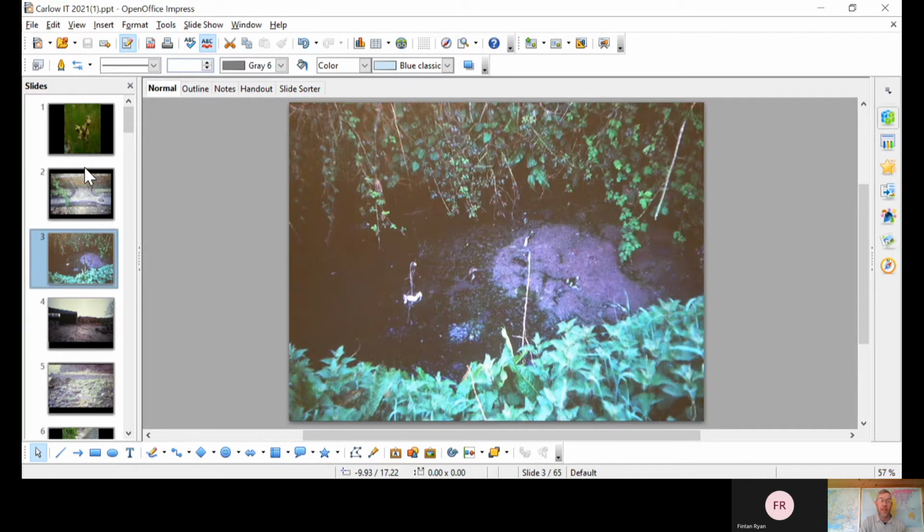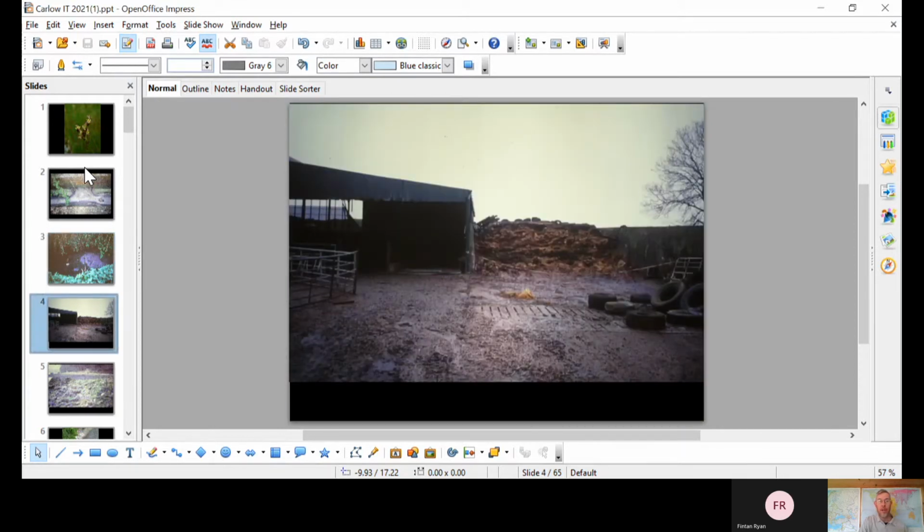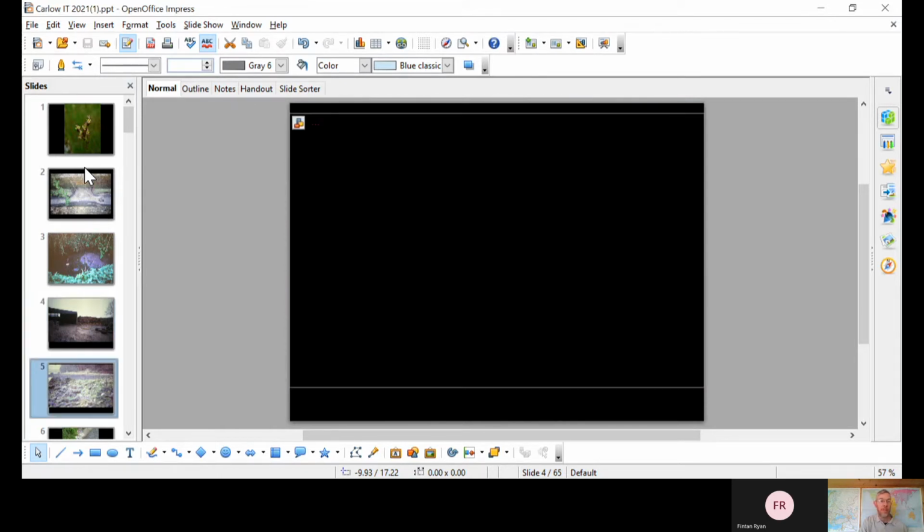That literally, it was just stripping the oxygen out of the water and fish were drowning. That was the cause. And still, BOD from yard runoff, from silage ponds, whether it's clean yard runoff or dirty yard runoff or slurry, any of that gets into waterways raises the BOD in the watercourse.